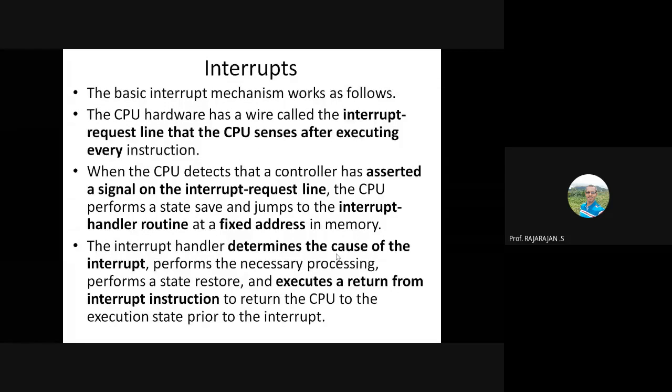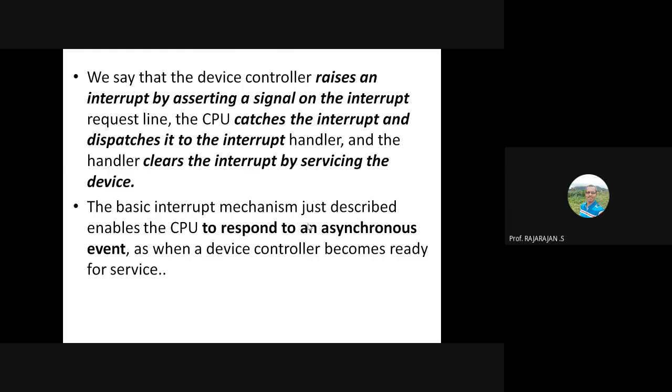The story of interrupts need not be explained again. What the idea of an interrupt is and how interrupts are handled is all well known to you. So any device can assert the interrupt signal, and the CPU after execution of every instruction will check whether an interrupt has occurred. If an interrupt is found, then it immediately transfers control to the interrupt vector or interrupt service routine, which contains the necessary code for handling any type of interrupt. All this happens as a response to the interrupt.